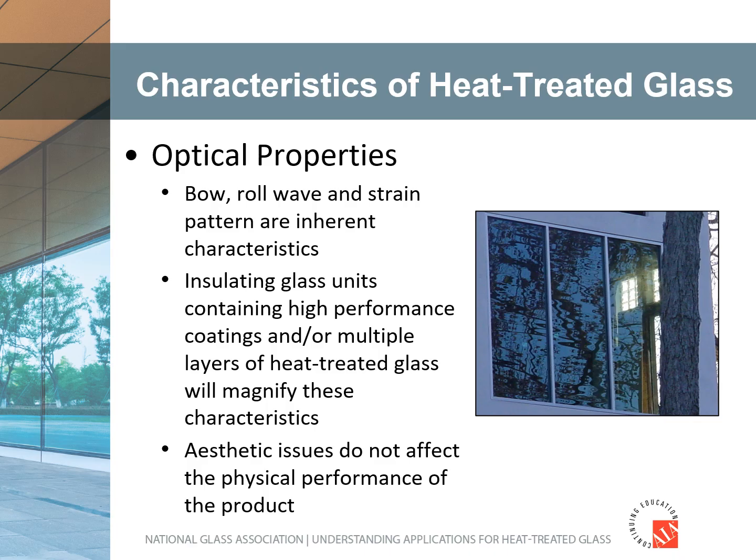The latter is a repetitive wave-like departure from flatness related to a horizontal conveyance system, heat treating process, excluding edge effects, and distortion influenced by assembly or installation. These deformations can cause aesthetic issues, such as undesirable reflections. While difficult to eliminate completely, these generally undesirable effects can be controlled and minimized with proper attention to furnace maintenance, loading practices, and quality control procedures.